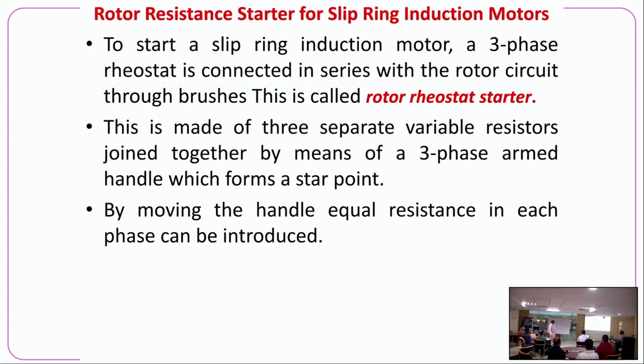Next one is the rotor resistance starter of a slip ring induction motor. If the induction motor is a slip ring induction motor, then the rotor terminals are available. On the rotor side, we can use rheostats for the 3 phases, and at the time of starting the motor, the rheostats in the rotor circuit are kept at the maximum value.